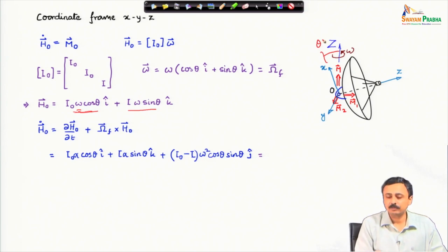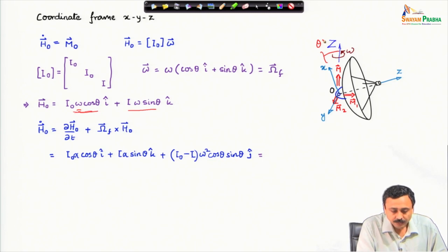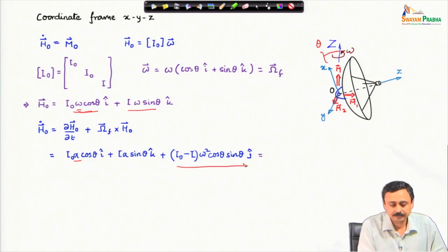It was mentioned in the statement of the problem that at a particular configuration, you can relax these considerations and then try out the problem. Therefore, theta dot has been considered to be 0 when I take del t. Only omega dot is considered, which is denoted by alpha, and this comes from the frame derivative, so, because of the rotation of the frame.